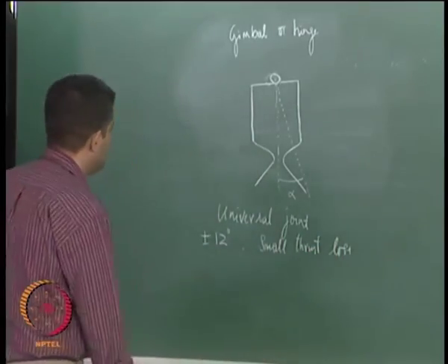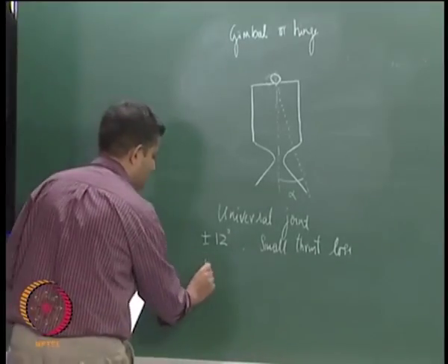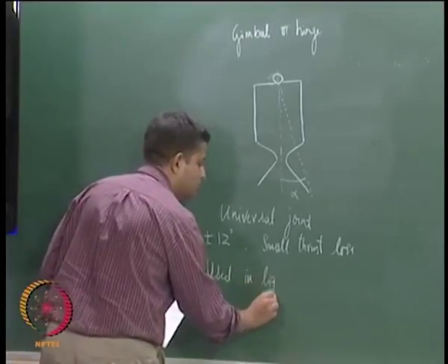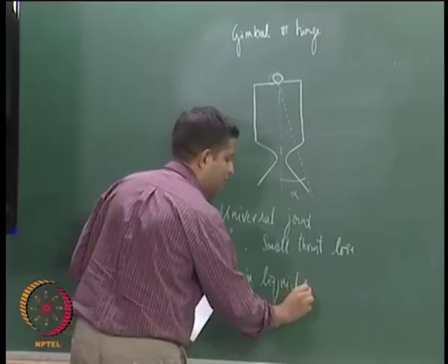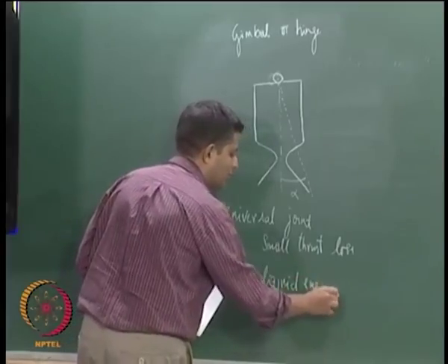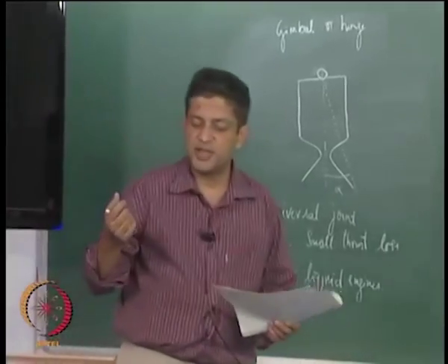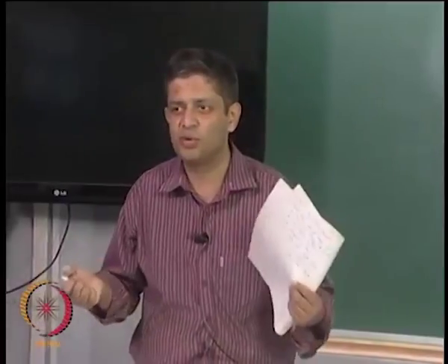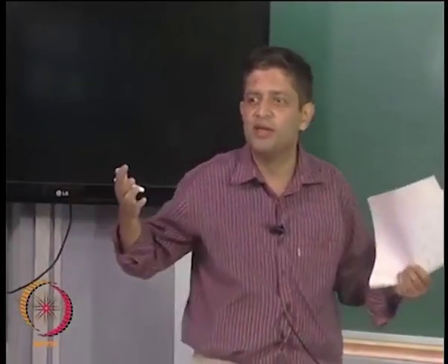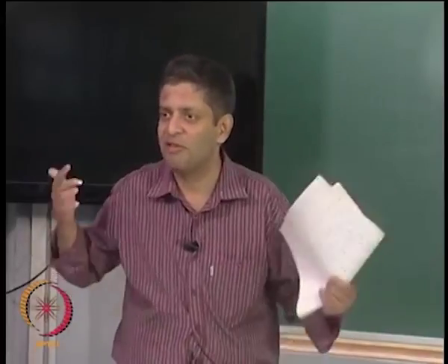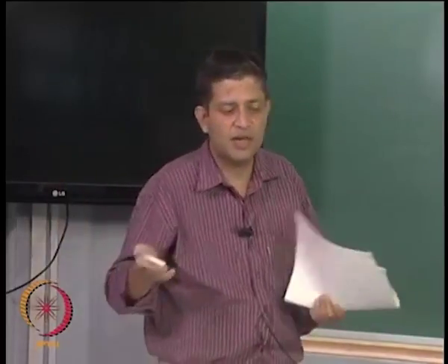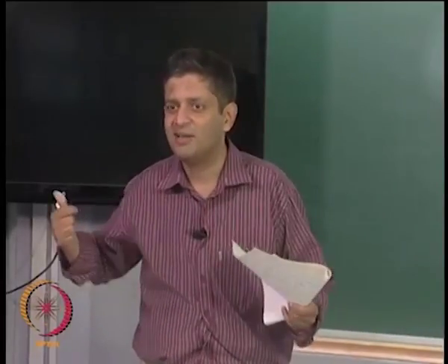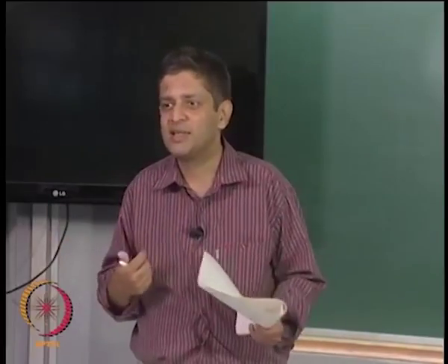and this is typically used in only liquid engines. That is because, as I said earlier, if you look at solid engines, the entire propellant is also inside the motor. So it would be very difficult to move the entire motor because the weight of the propellant is also there, whereas in a liquid engine the propellant is stored elsewhere, and the only thing is you need to have flexible hosing, otherwise it will not allow this kind of movement.